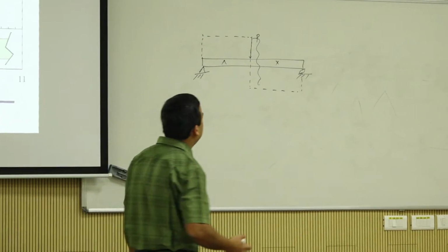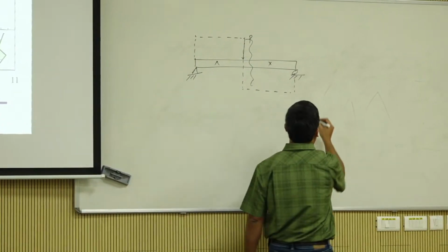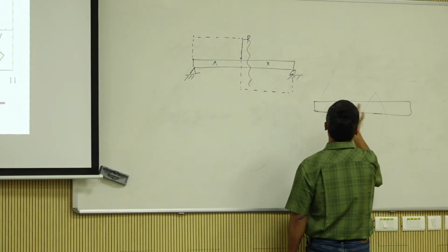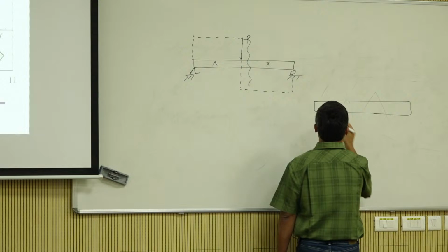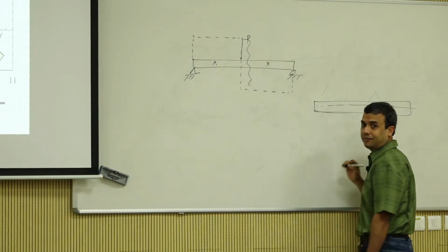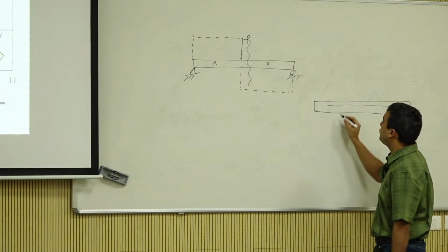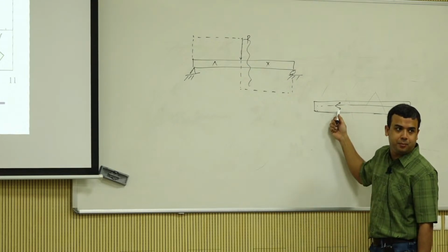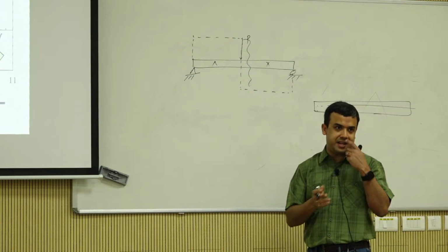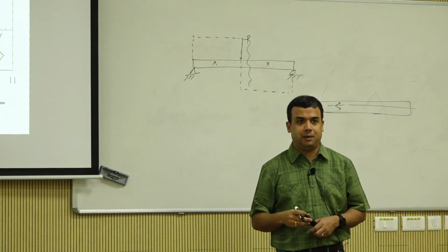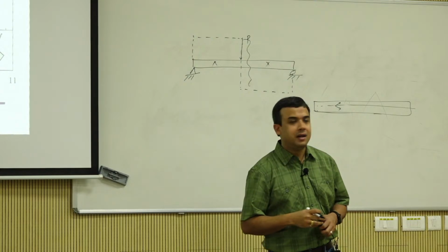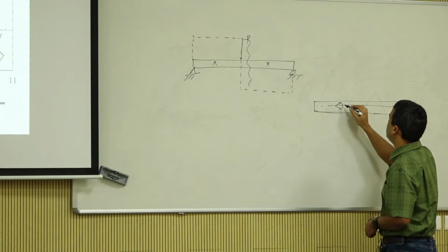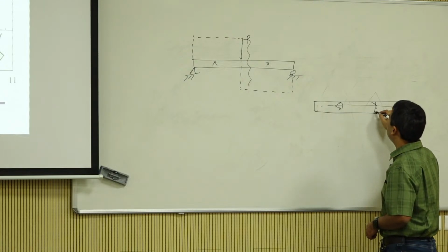What you can do on a railroad is you have the rail, it's a beam, right? You find the neutral axis, right? You install strain gauges, 45 degrees up, 45 degrees down. Why? Because at the neutral axis, the principal strains are oriented that way, right? And then you can actually take the difference of them. That will actually tell you the shear strain. Here also you will get the shear strain.